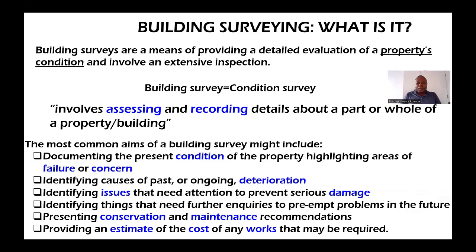identifying the causes of past or ongoing deterioration, identifying issues that need attention to prevent serious damage. There are times that if there is a defect on a property, if you don't take immediate action, if you don't evaluate the property to identify the main issue, it might escalate from minor to major damage. Identifying things that need further inquiries to preempt problems in the future, presenting conservation and maintenance recommendations, and providing an estimate of the cost of any works that may be required.